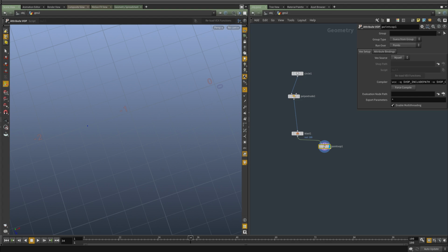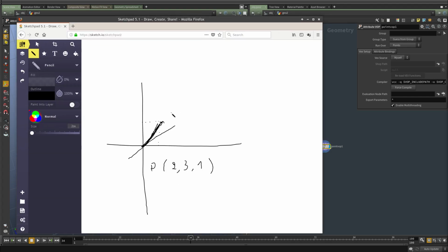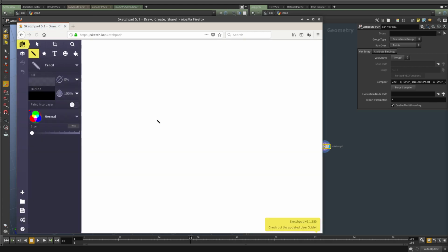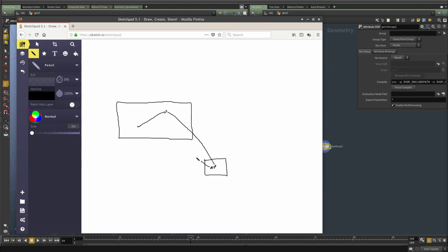The remapping is very, very simple. Let's open the sketchpad again. So let's say you have your screen. It is 1920 by 1080, for example. And then you have the mouse, or whatever you're controlling the screen with. You move the mouse this much, from here to here, and the cursor moves from here to here, and this is what a remapping is. It takes this distance that is between 0 and 0.1, for example, and remaps it to 0 to 5. So when you move your cursor in a small surface, you can remap it to match this. This is what fit range or remapping does.